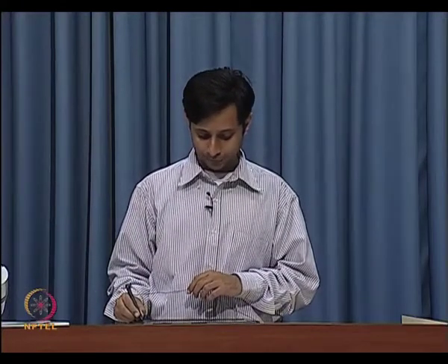An engineer is going to do what is easiest to do, right. That is the training that you are supposed to be getting as an engineer. Engineers like to do the easiest thing. So, there are many ways of finding the input referred noise voltage. Foolproof: find out the output noise voltage, the mean squared noise voltage at the output divided by gain square, that will give you the mean squared noise voltage at the input that you should have applied to a noiseless circuit to get the same output, which is basically the input referred noise.